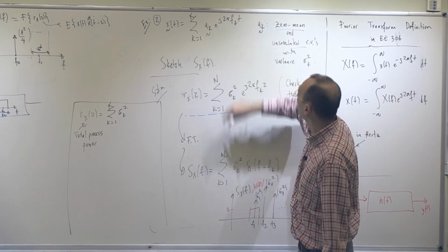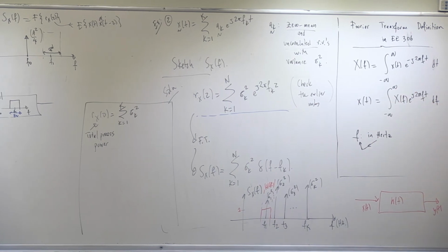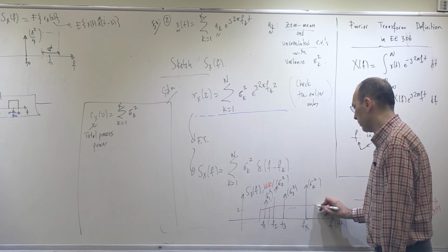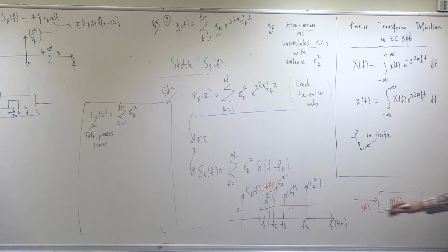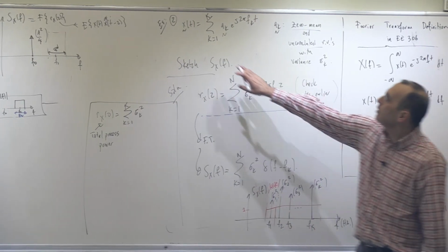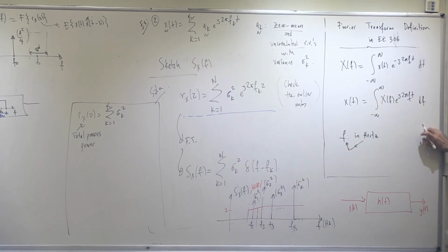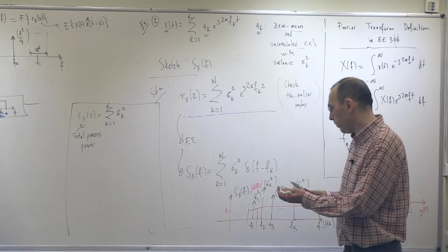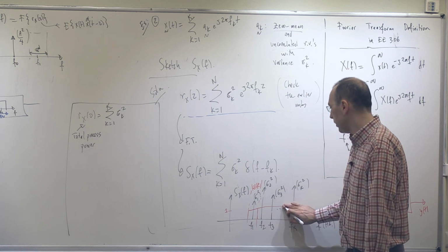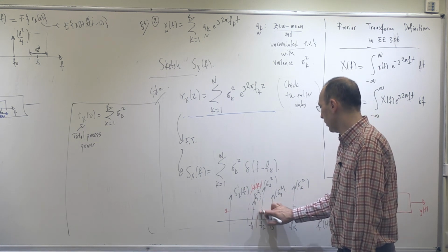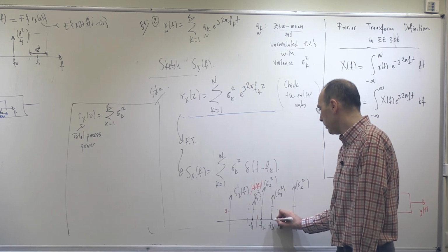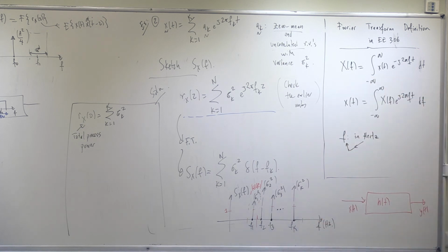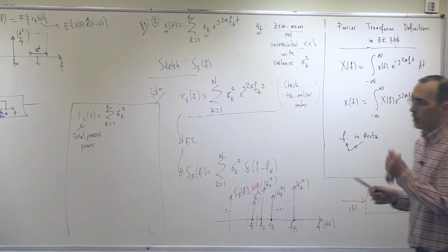It will be selecting the first component in this sum. So we see that now this power, if this filter's bandwidth is very large, then at the output side I have a random process which will be passing through all of these components, meaning that this process passes through without any attenuation or amplification to the output. That will be it. Now we see why this is called power spectral density, a little bit more. Because what we see is the process power is concentrated at these discrete locations on the spectrum. Okay, process power has that kind of a concentration.